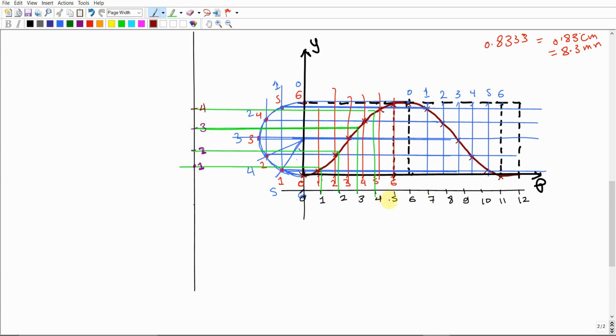And repeat again. If we're going up with the 5, by the way, it is not necessary to draw a vertical line every time. You can just put the ruler or the triangle, mark a point, and draw a horizontal line this way, then locate another mark. So this is going to be the 5th mark. Make sense? Then for the 6th mark, as you can see, if we draw a vertical line, it's going to coincide with this line.